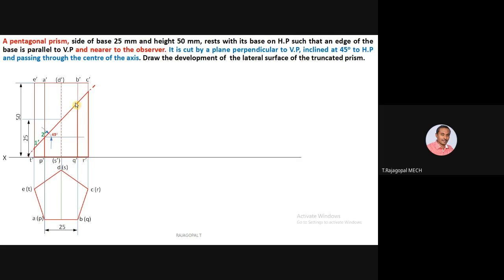Wherever the section plane cuts here must be the third cutting point, 3 dash. Next, if you check CR, C dash R dash, this is where the section plane is cutting. Make it 4 dash. Finally, D dash. It is a hidden corner from here, an invisible corner, that's why we mark it by means of a hidden line, small dashed lines. Make it 5 dash, represented in brackets due to the invisible corner, invisible longer edge. So these are the 5 cutting points of the section plane.